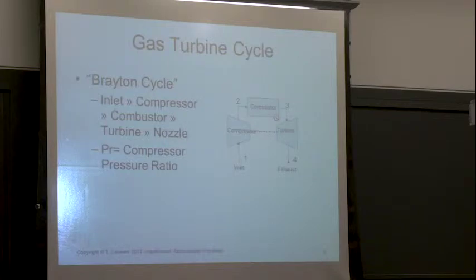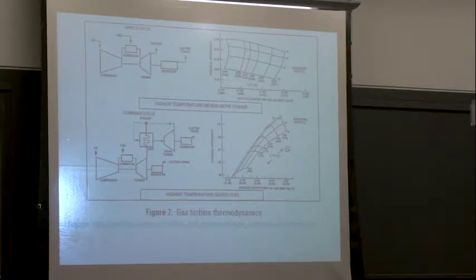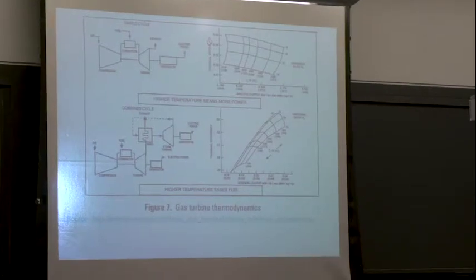Well, now let's go back to this picture here, whether you're over here or whether you're over here. And we've just talked about how, if you're a simple cycle and you want better thermal efficiency, you want higher pressures, right? And what do you all know about auto ignition times, how they scale with pressure? They go down, right? Roughly as 1 over pressure. So if you go from 10 atmospheres to 50 atmospheres, you just dropped your auto ignition time by a factor of 5, right? So think about a modern aircraft, and what also happens when you're pressurizing the air, not only is the pressure going up, but the temperature is going up, right?